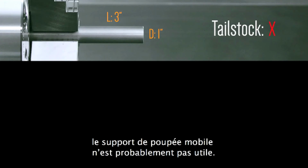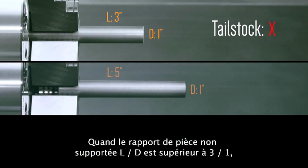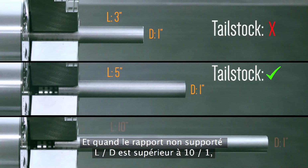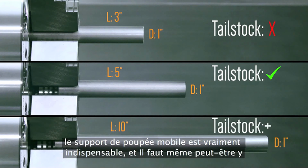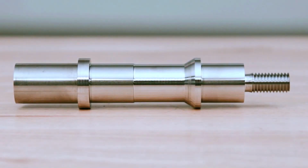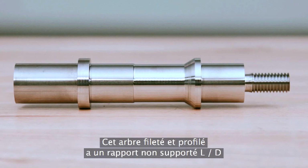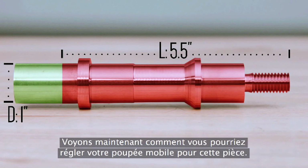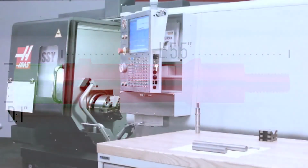not needed. When a part's unsupported L to D ratio is above 3:1, now it's time to start considering tailstock support. And when unsupported L to D is over 10:1, we'll definitely need tailstock support and maybe something more, like a steady rest. This profiled and threaded shaft has an unsupported L to D that's beyond what is typically possible without a tailstock. Let's look at how you'd set up your tailstock for this part.